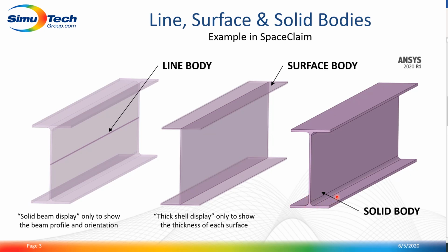On the right, for the solid body representation, we will use either hexahedron or tetrahedron finite elements to discretize the geometry, and you can see this method as the simplest way to model a part, but this will often lead to more equations to solve in the model.